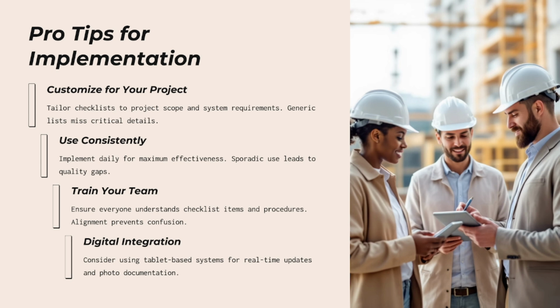Suppose you prepare a basic checklist and you regularly visit the site for that particular work, checking whatever the workers are doing. Through that, you can understand: are they following the works as per the standard? Are they using the approved drawing? Are they using the shop drawing? Are they using the approved material? So from there, you can build your own checklists from your own experience.